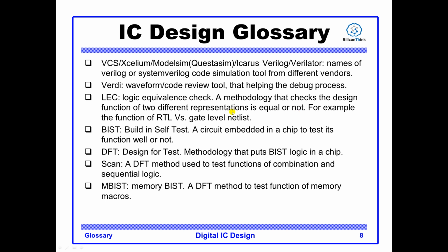For example, we can check the function of the RTL design and the gate-level netlist to check whether they are functionally equal or not. BIST, built-in self-test. This is a circuit in the design to test whether the function of the chip is okay or not.